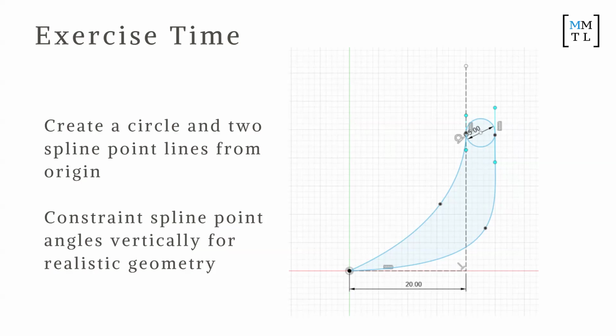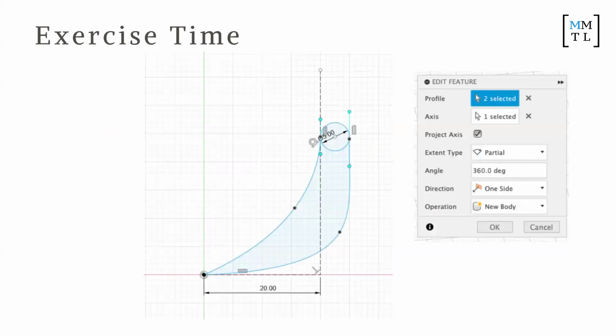Yeah, so you can all finish up the sketch, so exit out of the sketch menu. Finish the sketch. We're gonna move into the solid modeling. So basically you click the revolve tool in the solid modeling tab. And then now you want to choose your sketch profile. So you want to choose both the circle and the bit underneath. Or you can try clicking one of them and see what happens.